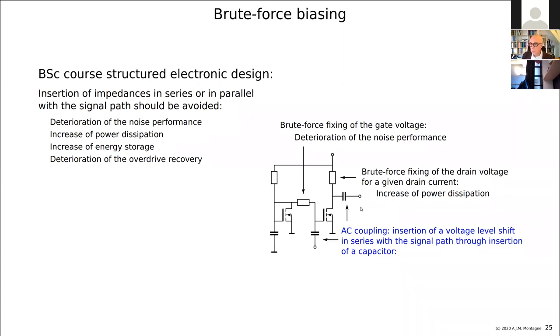Maybe you remember that when I introduced this AC coupling and there was a source connected to here, we said, well, if you power up the amplifier, then these capacitors first have to charge, and this one has to charge. And when this is charging, basically the voltage is not yet good. So the device is not yet biased in the correct way, and the amplifier is not working. That's a kind of startup behavior.